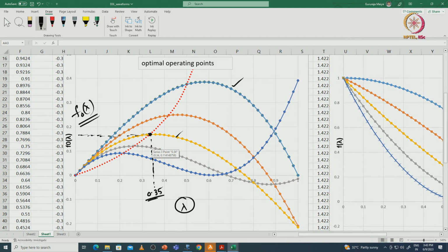With respect to 0.35, the difference between d_is and d naught s will be very small, like if the lambda value is very small, the space for the rotor is coming down. Because of this reason we have concluded the lambda value should be 0.4 to 0.75 to make the design feasible with respect to the rotor also.